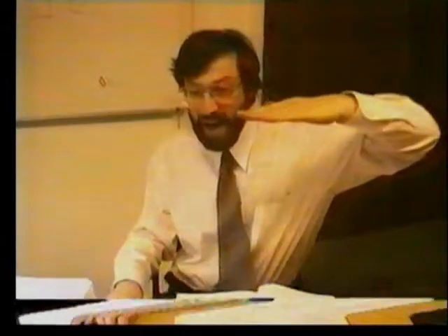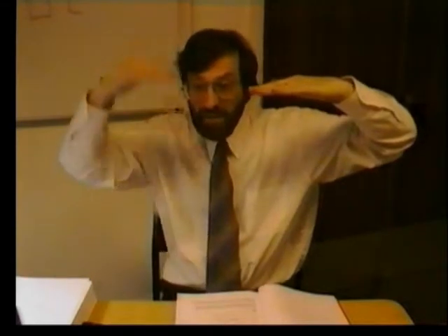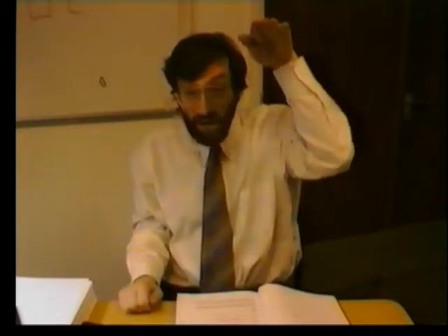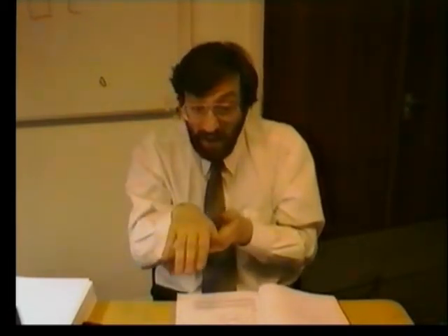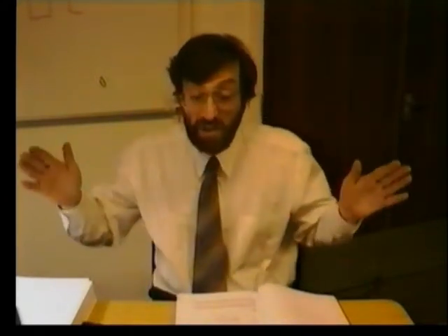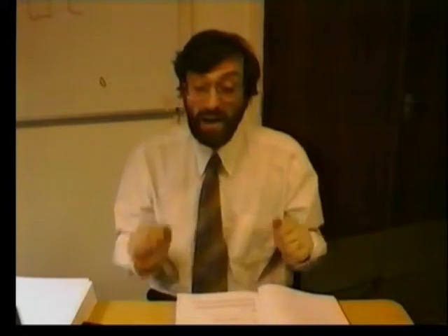The idea is here's our unknown voltage, and we try out different values in turn, going down in the binary pattern from a reference. We first try 8 volts, 4 volts, 2 volts. And then if you want more precision, 1 volt, half a volt, quarter volt, eighth of a volt, and so on and so on. The more tests you do, the greater the precision of the conversion and the more accurate your result. Successive approximation is the technique of trying out a series of possible trial voltages in a binary changing mode, smaller and smaller binary divisions of the reference voltage.